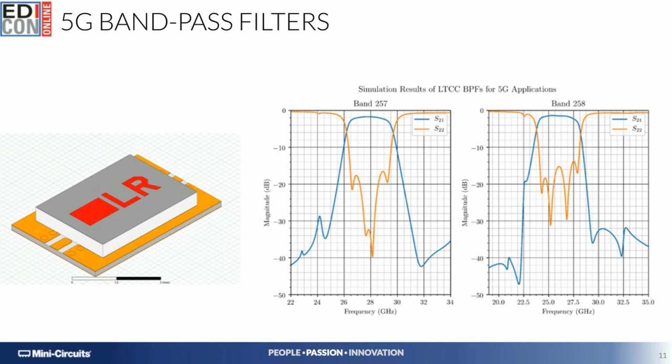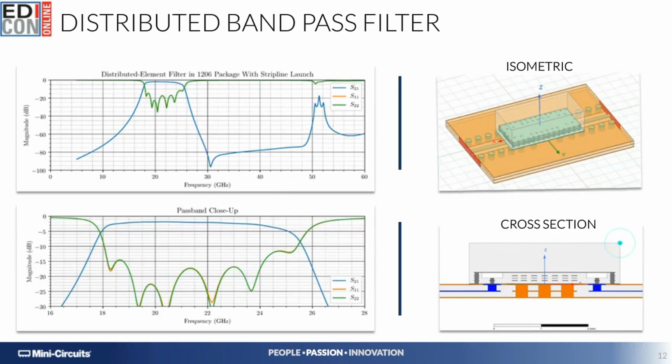Mid-band insertion losses close to 1.3 dB, much deeper broadband stop band rejections, below 30 dB at frequencies as high as 30, 40, even 45 gigahertz, although these simulation results are limited. But I may be available offline to provide you with much broader band simulation results on the same. Sustained performance at frequencies beyond X-band, and again, we intend to provide surface-mountable shielding structures as required. Here's another example of a distributed bandpass filter realization.